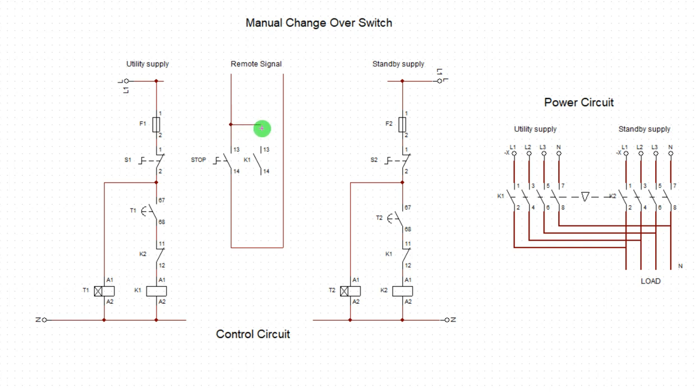Remember, I taught you start station. So this is start station. It's going to be in parallel. Either this one is closed, the gen will shut down. If this one also closed, the gen will shut down. This one by manual, shutting the gen set manually. Then this one is shutting down automatically. Remember, take note that when the mains is working, when the main is active, this one will shut down. So the gen will be shut down.